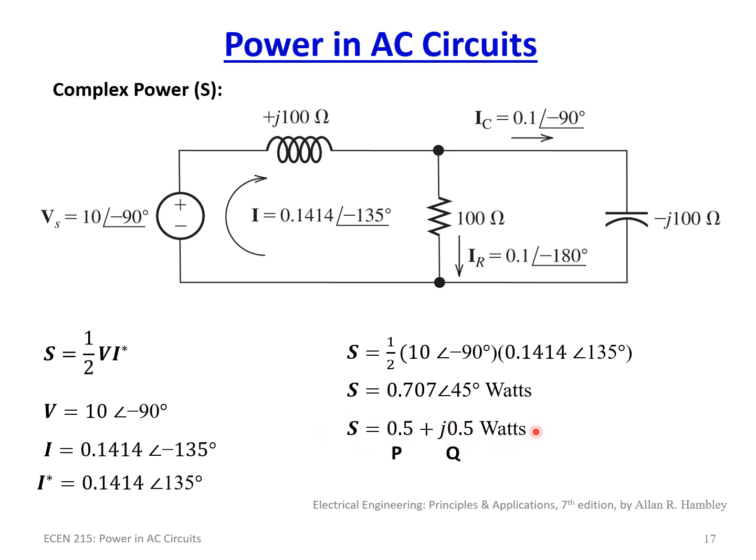Now again, in complex vector form, this has units of watts. If you took the magnitude of this, which is this 0.707, and you were going to describe what is the apparent power of this power supply, what is being supplied, the apparent power is 0.707 volt amps. So this has the units of volt amps. This entire S has the units of watts, but the individual component P has the units of watts, and the reactive power part, the imaginary part, Q, is half a var.